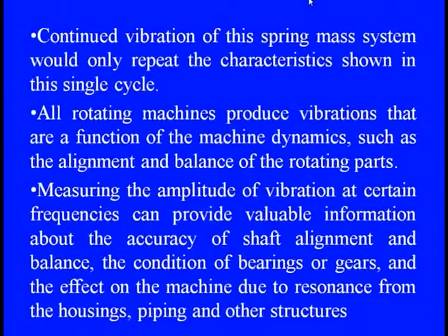Because measuring the amplitude of vibration at certain frequencies provides valuable information about the accuracy of shaft alignment, and also the balancing condition of these rotating masses like bearings and gears, or the effect on the machine due to resonance from housing, piping and other structures. And when these devices are under exciting forces, clear exciting frequencies come out through the transmission features of the machine, and we can measure and characterize the kind of excitations from that.